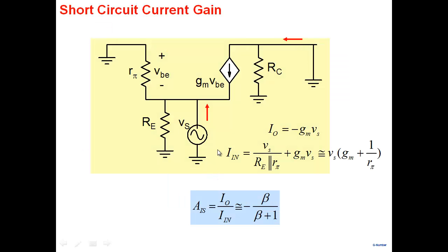All right, sometimes we also calculate, besides voltage gain, input resistance, and output resistance, the current gain. Sometimes you'll see in books calculations for short circuit current gain. So you take the output and you short it. This is the current that flows in the output if you short the output here, and this is the current taken from the source here. And you can easily derive and show that the current gain is less than 1, because you're forcing current into the emitter and you're taking current out at the collector. The emitter and collector gains are less than 1 here. So anyway, if that's of interest, one can easily calculate that here.